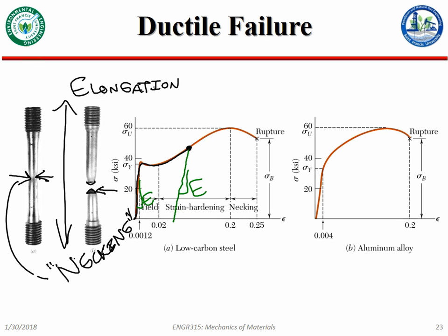So just as in the proportional region, inside of the proportional limit, it'll respond according to Hooke's law. So kind of like sigma equals E epsilon. It'll respond like that there. In kind of the same way, it'll respond here. It'll just come back to a non-zero strain.